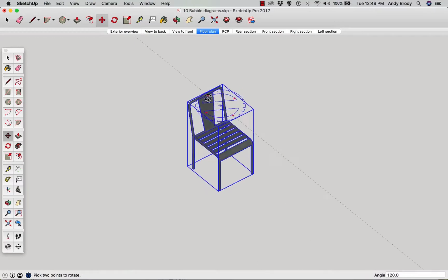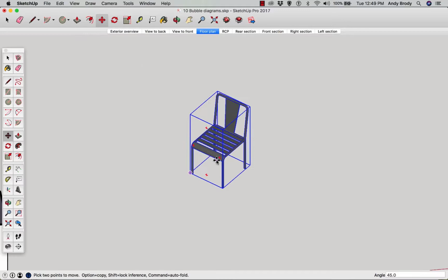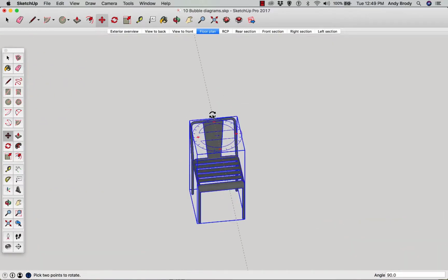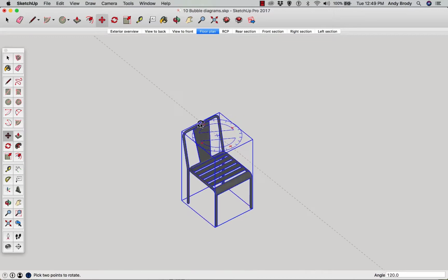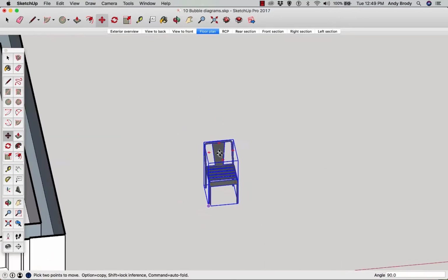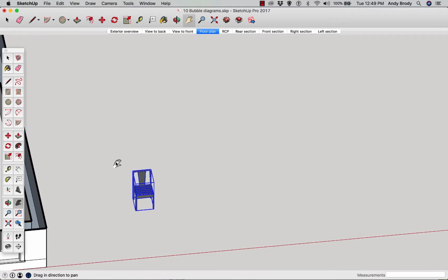Anyway, these grips up here, the little plus signs, are rotate grips, and those are really nice to make little subtle changes. There is a snapping which happens. I believe my snap is set to every 15 degrees. So that's a basic way that you can modify the chair. Now, if I just want some straight rows, for example, I can use my Move command and tap Control, or Alt on a Mac.